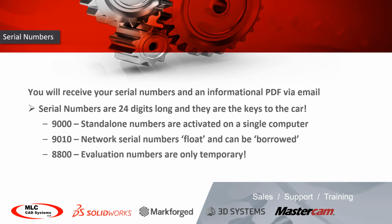Finally, you may have had an evaluation of SolidWorks so far. Those serial numbers start with 8800. If you've installed one of those, you want to go ahead and replace it with one starting with a 9. Just find your installation of SolidWorks in the Add or Remove Programs list. Right click it like you're going to uninstall, but you can choose Change, and you can just swap that serial number out with a commercial serial number.